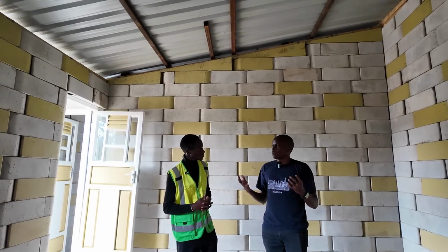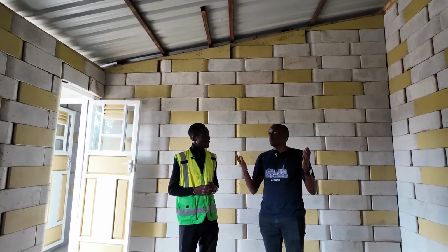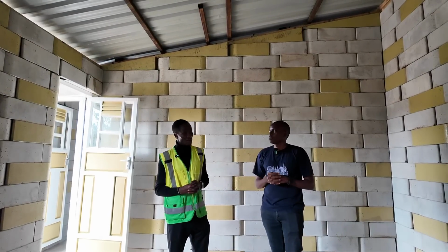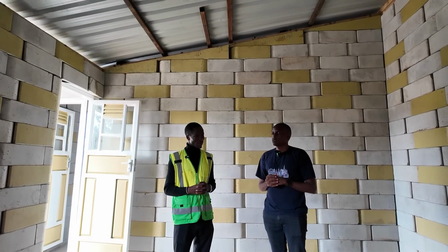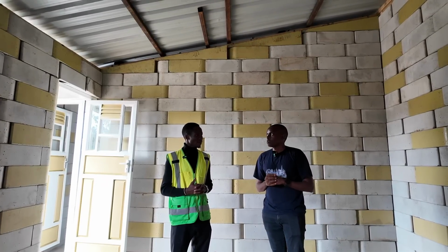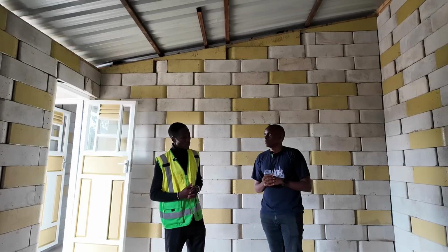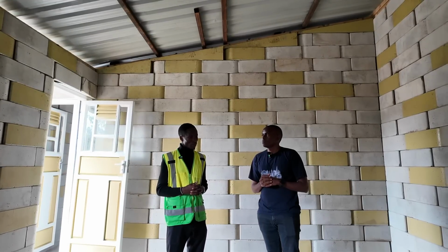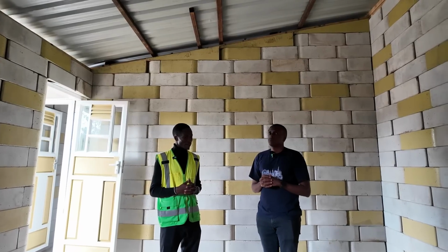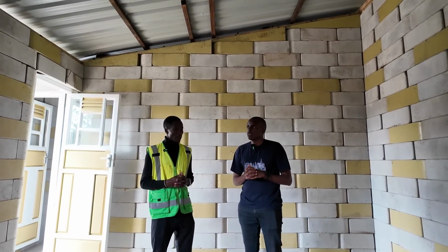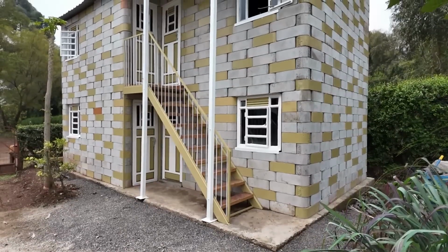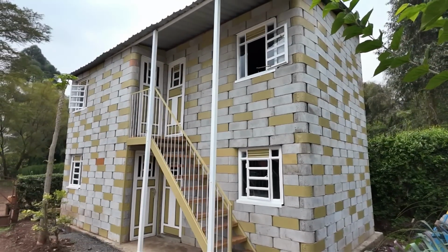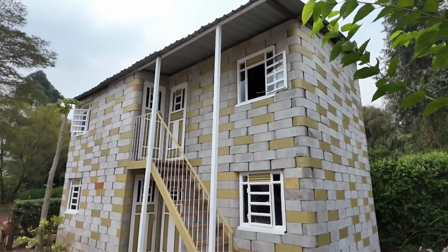And for those clients who want complex pitched roofs, is it possible with the twist blocks? Yes, it is very, very possible with the twist blocks. If you want a complex pitched roof, we do structural detailing for the roof itself to ensure that it's able to bear the wind loading and such. So we detail it properly and integrate the trusses as the client has perceived. Then you're able to install the roof, so it works with any type of roof.